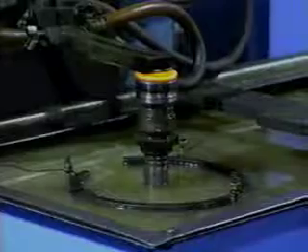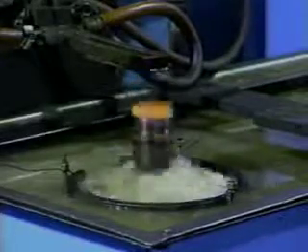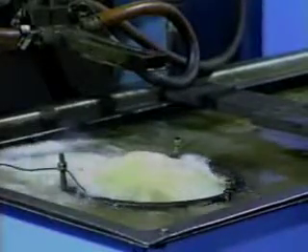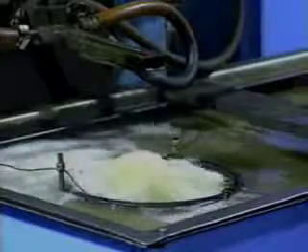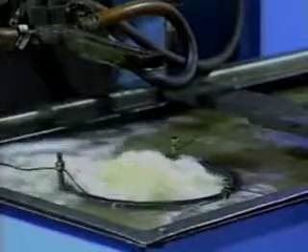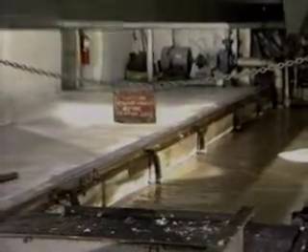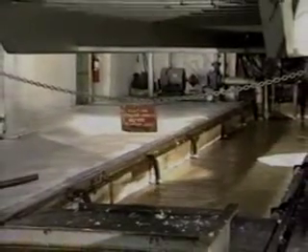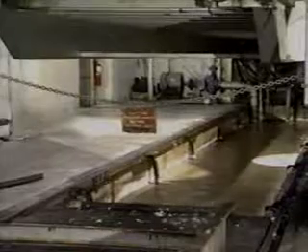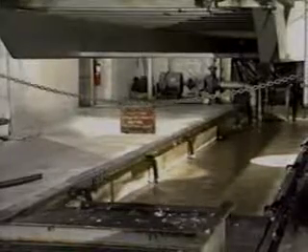Although there are induction heat treating processes which employ a manual dunk and agitation as shown here, most processes employ either an open or submerged spray. In all cases, it is important that the quenchant reservoir be large enough to allow the foam head to be drawn back into the system. If the reservoir is too small, the part will be quenched with a mixture of foam and water, which will lead to an increase in distortion as well as a decrease in hardness.